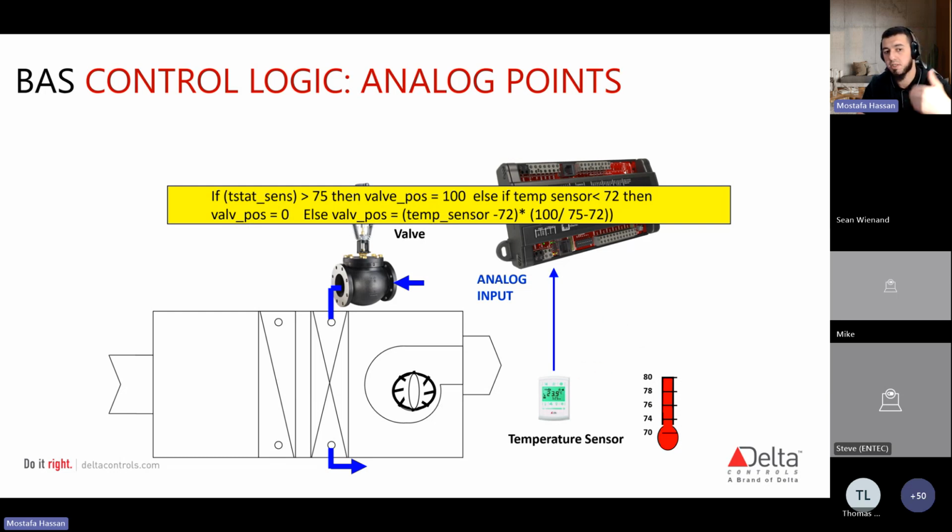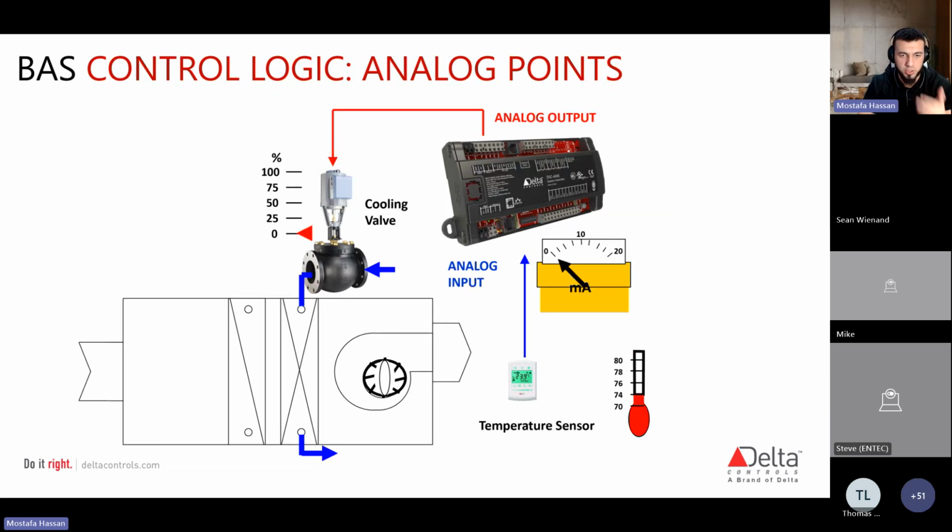So anyway, the temperature is sensed to be high, hits the controller, and the controller says, let's open that valve, right? So let's open the valve is not actually an analog input, but in this case, we're going to do something different, right? So we skip that, right? So we turned on the valve, that's a binary, right? So turn on the valve is binary or digital. Now controlling the valve position, that's where the analog output happens, right? And that's what's shown here.